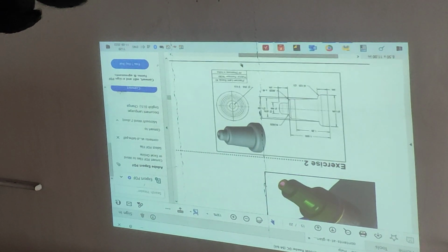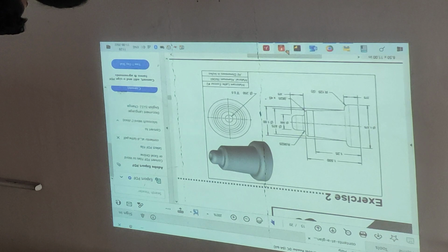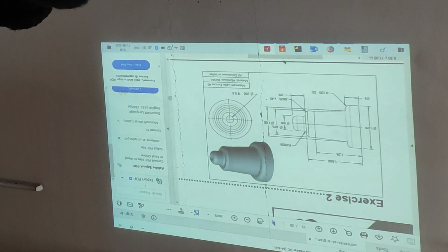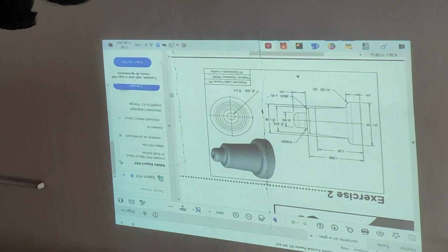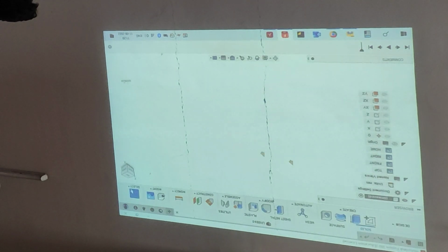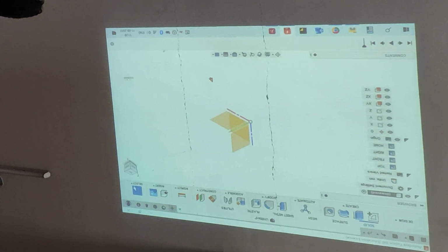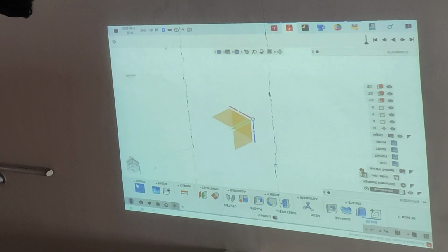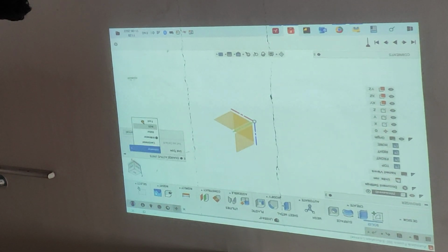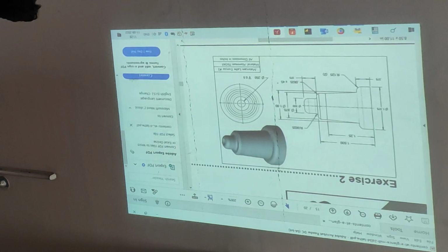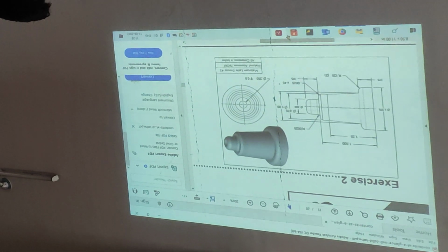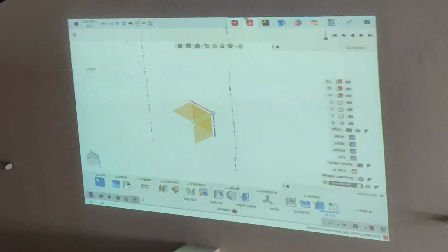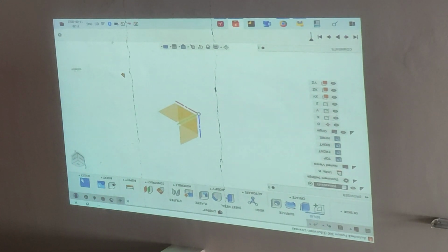Okay, let us create this, and I think you have already done it, but let me do it. So we can make a sketch, because everything is sketch driven here. It's a sketch based software. So first I will change my units to inches, because my PDF drawing is in inches. Here it is provided as inches. So I am going to draw the sketch and make use of that sketch for further modeling.